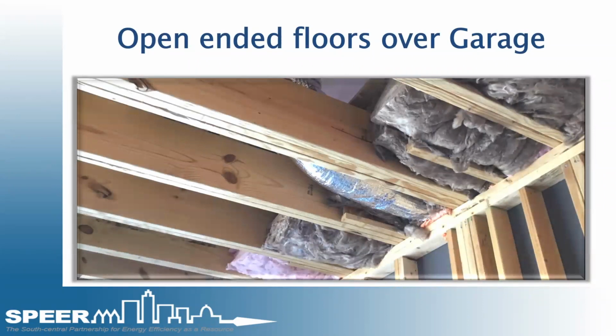So, open-ended floors over garage. I saw this a lot. It's basically either a media room or a foyer that pushes out over a garage. It's a second floor that extends over the garage just shortly, 1.5, 2 feet at most. But you've actually got to make sure that that is also 6-sided encapsulated.